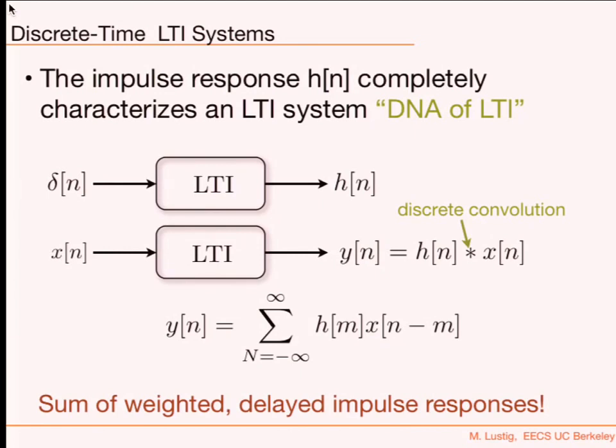Basically, for LTI systems, if you give me the impulse response, the output is just going to be a weighted sum of delayed impulse responses. Whatever the input is, I'm just going to attach an impulse response to it and add it to the rest. Another sample comes in, I attach an impulse response and add it, and so on and so forth. Add them all together, and that's going to be the output. Extremely powerful. Let me give you an example.